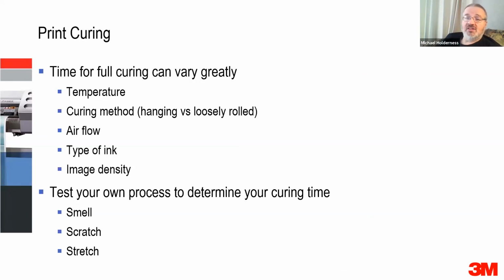Smell it. The scratch test. So run your fingernail over it. If your fingernail grabs and chatters across the surface, then it's still wet. Stretch it. If it feels stretchy, then you know that's probably not fully cured. So ultimately, you guys are going to be the judge as to whether your print is correctly cured.